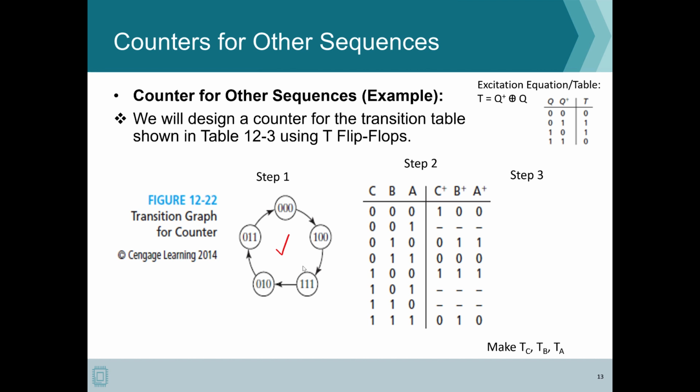So this is basically a very generic simple counter, and since it only has about 5 states, you can call it an arbitrary mod 5 counter, which stands for modulo 5 or modulus 5 counter.